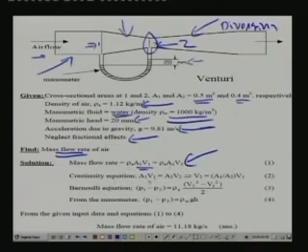So, from this equation you get that A1 V1 is equal to A2 V2, or the velocity at point 2, that means velocity at the throat, can be expressed in terms of the cross section areas at the throat and at the inlet to the converging section, and the velocity at the inlet to the converging section. So, V2 is equal to A1 by A2 into V1.